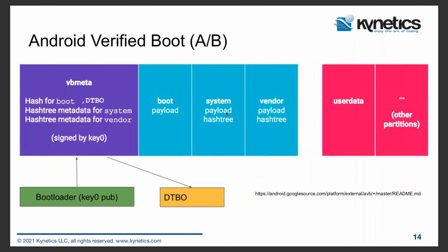So this is another slide on Android Verified Boot. So again, here from the bootloader to the user data, everything is controlled by a series of hashes that are contained in this partition called vbmeta that is signed by a key that is actually stored in the bootloader. Again, even the bootloader can be signed. You've got to use the fuse bits of your system on a chip, of course, and this actually will take you on implementing the full chain of trust.